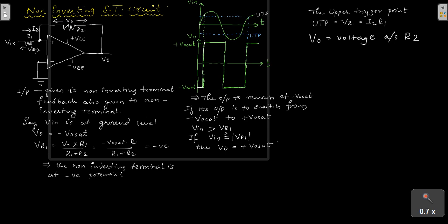I have already marked it here, right? So the current through R2 is obviously equal to I2. There may be a small bias current, but most of the current will flow through the load here. So I2 is equal to the modulus of V naught divided by R2; I am taking the modulus because it would otherwise have been in the opposite direction.